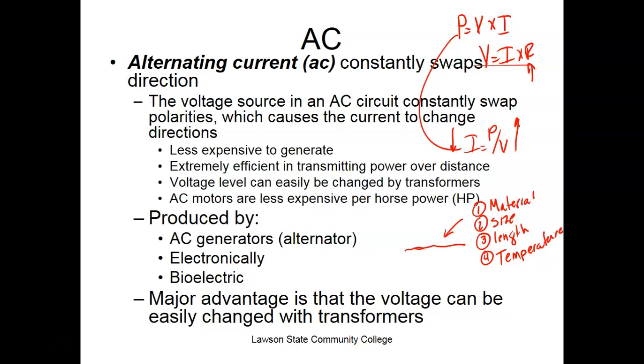But what's the problem with high voltages? Very dangerous, right? And they're also all looking for earth ground because power is generated relative to earth ground. So this is why these high voltage lines are way off the ground, right? You understand? So we can't get to them. And also they usually run in groups of 3 conductors because one conductor would be really, really big and it would be hard to pull and hard to run.